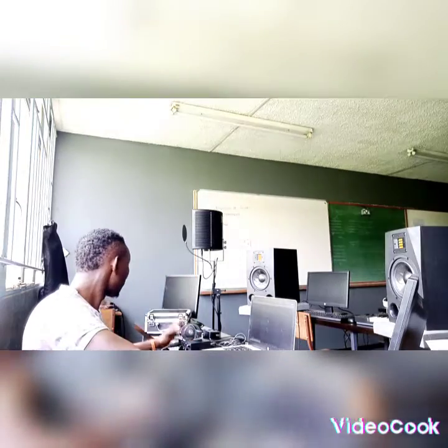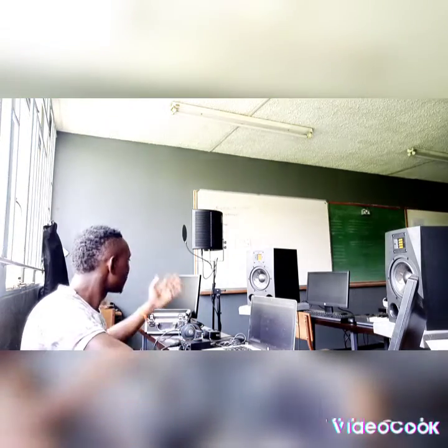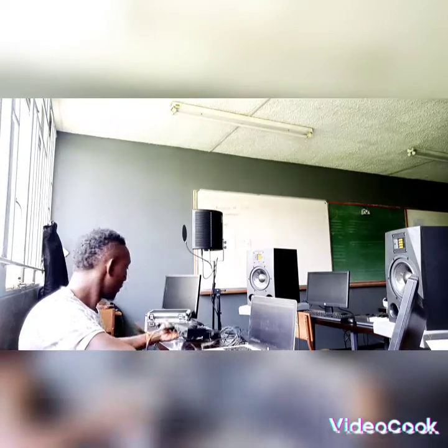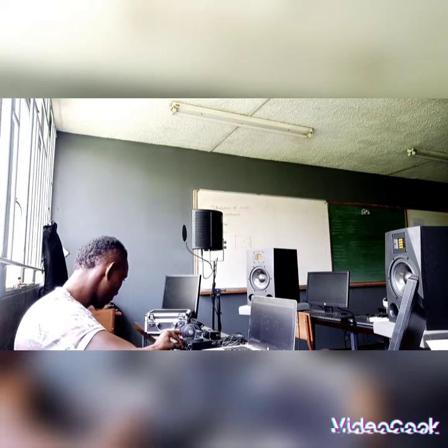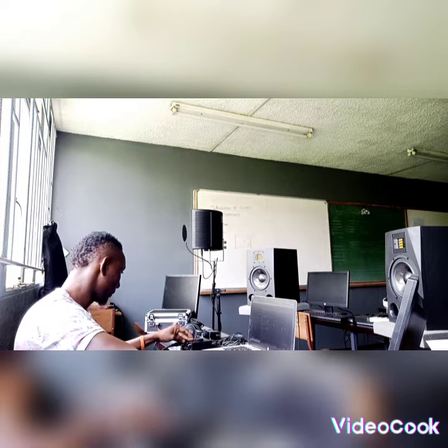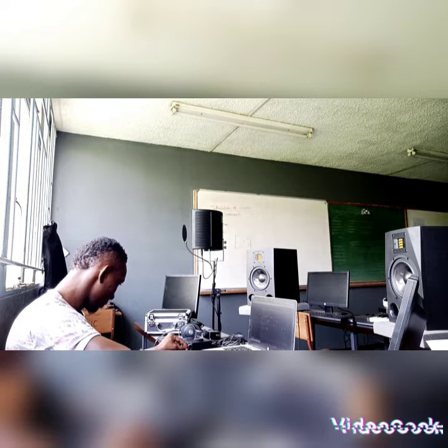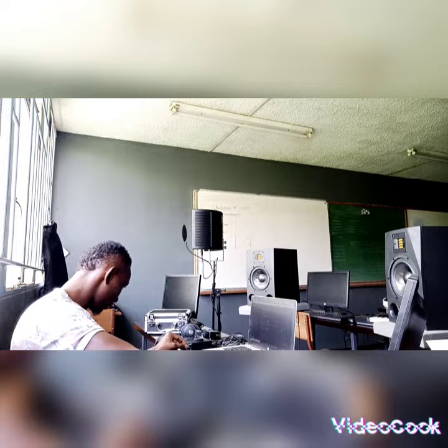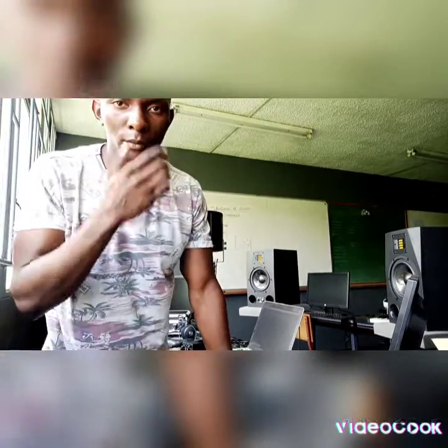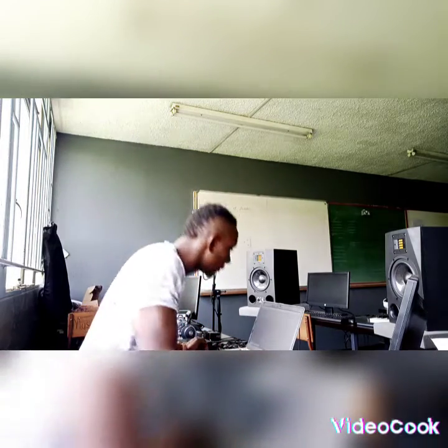Because we are using a condenser mic, we are not using a dynamic mic. We need phantom power, which I'm using channel 1 here on my interface. I know it's a bit down here, so I'll increase the volume a bit and push in the phantom power. It takes a bit of time, but definitely comes. Let's see if we can get ourselves from the speakers. Okay, so since everything is routed now, let's trace from the signal to the microphone.